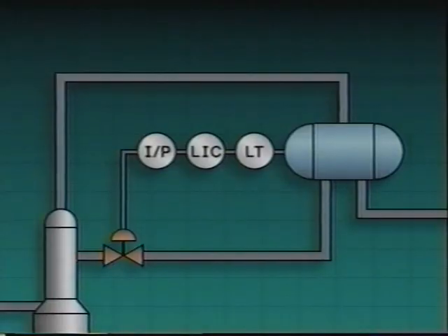As we just saw with the half-splitting method, each question or test reduced the remaining number of possibilities by half. The half-splitting method can also save a lot of time in the troubleshooting of industrial processes. It's especially useful for troubleshooting control systems. We'll use a reflux control system for a distillation tower to illustrate the point.